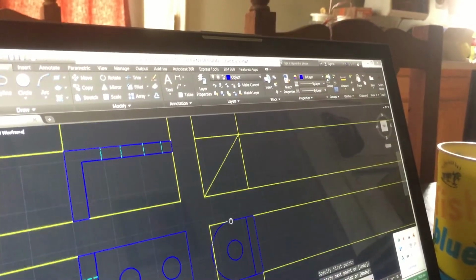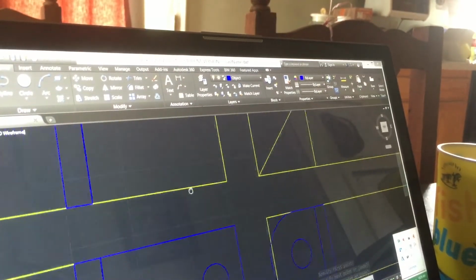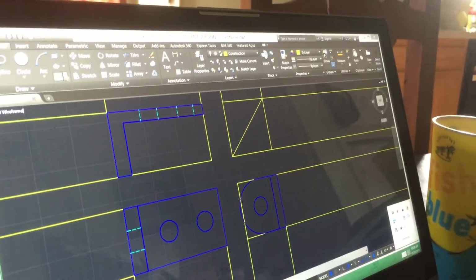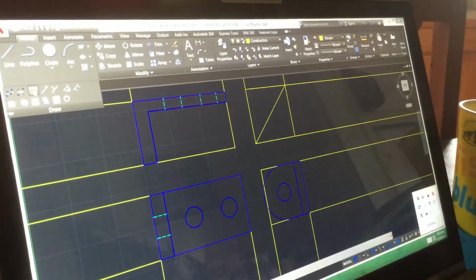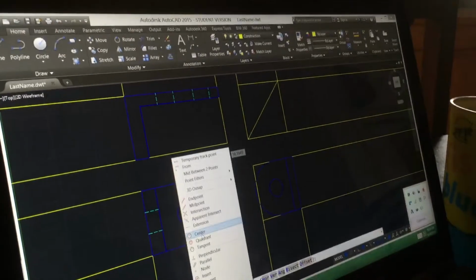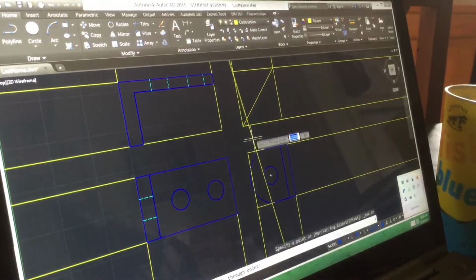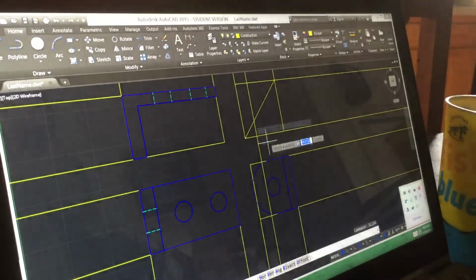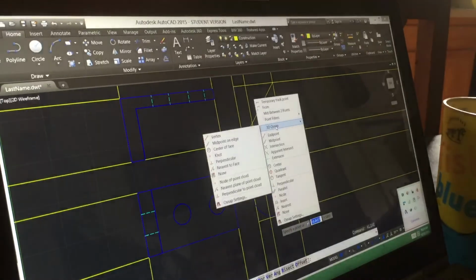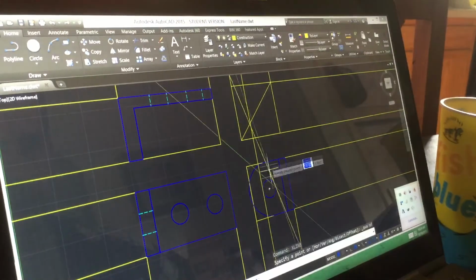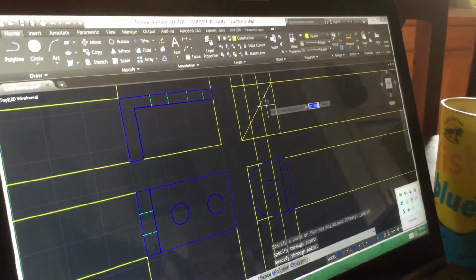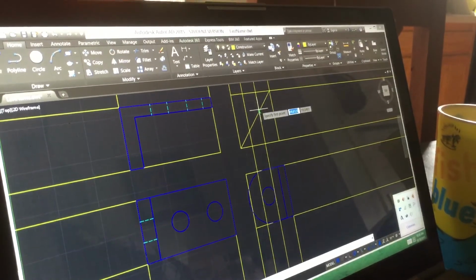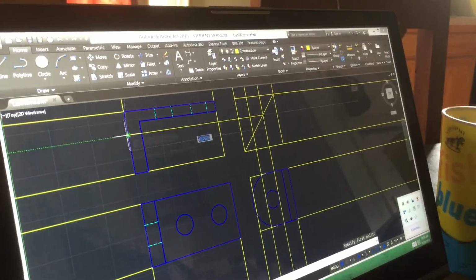And now to move this circle up to this view, I'll come in here and I'll grab the construction lines. I'll use my X line. I'll go from the quadrant up. Repeat that. Up. And then I can draw my line straight over.